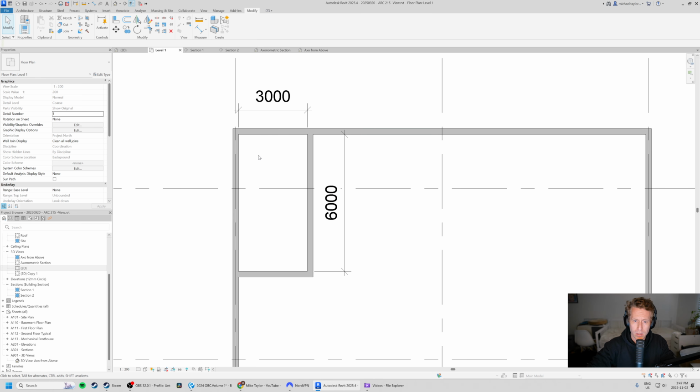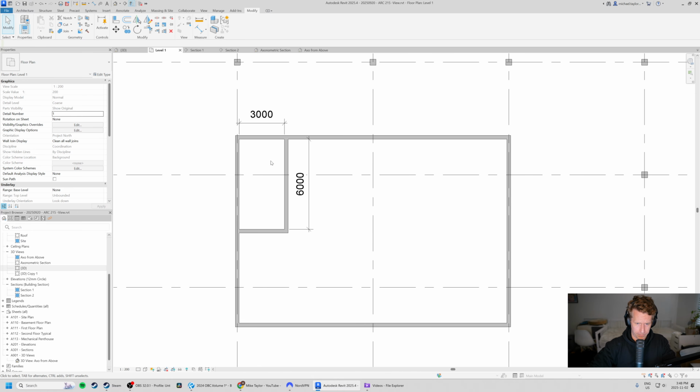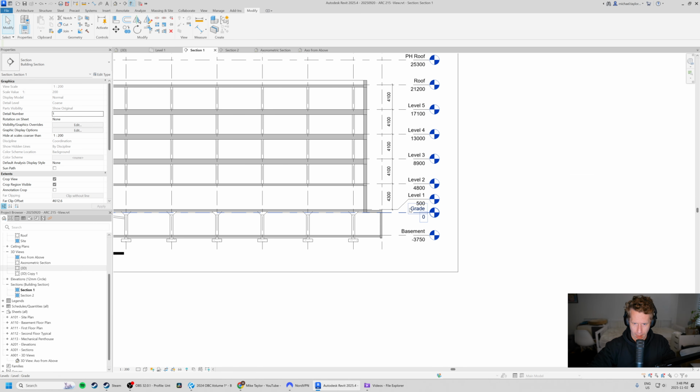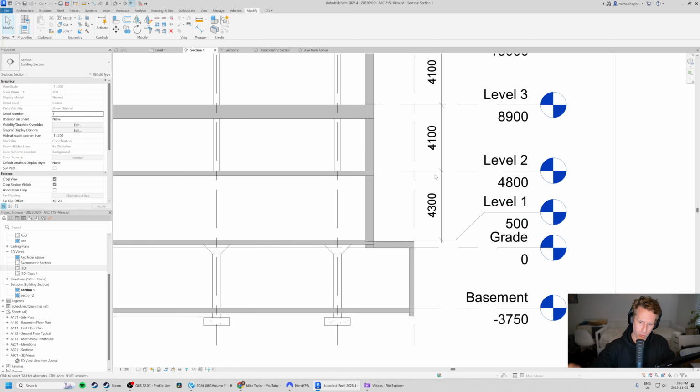Okay, cool. So why is that important when we're looking at stairs? Well, we do want to make sure that Revit has some simple systems that automatically calculate our rise over run or our riser heights while we do this. It makes it very, very easy. And I might argue this sense of automation, fantastic. So first things first, we should check our levels. So let's just jump over here to section. I'm going to start by doing a stair from level 1 up to level 2. We'll keep it real simple.